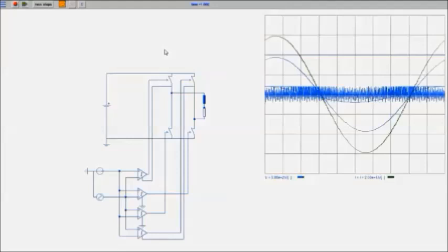So you can even further increase the sampling rate of the calculator. You can further increase the frequency of the signal generator. And basically today you go up not only to 1000 or 10,000 Hertz, you go up above 20,000 Hertz, so there is no audible noise anymore at all.